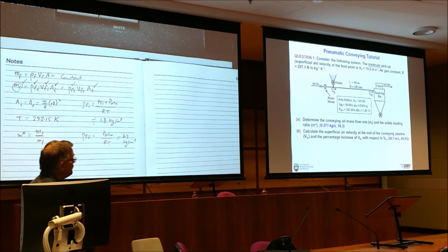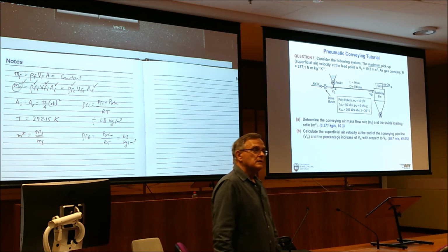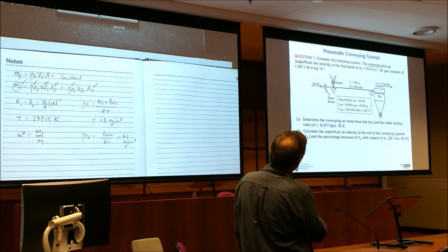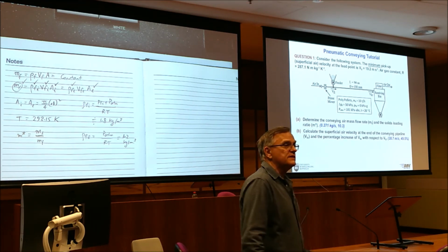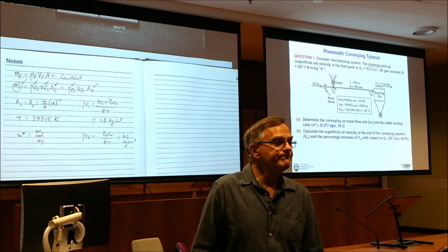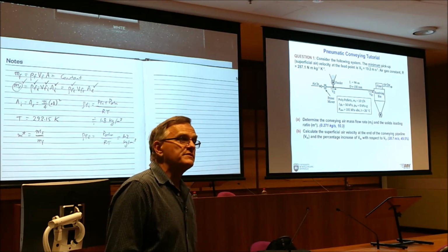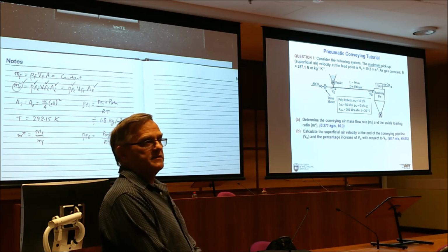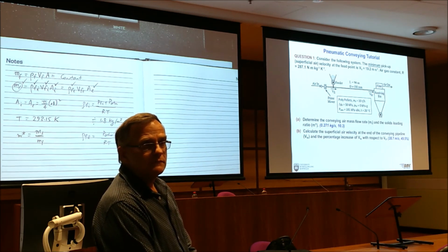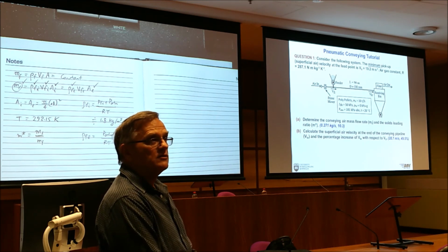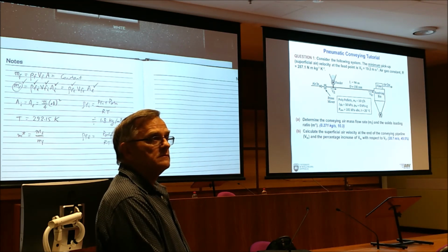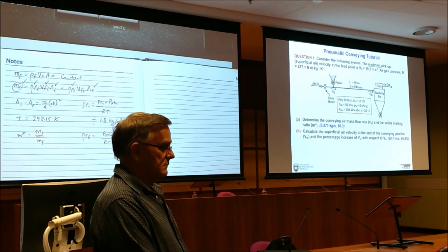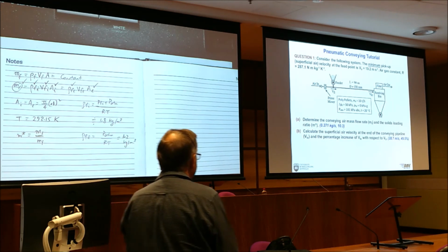28.7 metres per second. Right, so the air velocity starts off at 19.2 and it increases steadily up to 28.7. And that is almost a 50% increase, as I indicated before. If your gas density changes by 50%, your velocity will also increase by 50% due to continuity. Rho v is constant, remember that, okay? Because your areas cancel, AI equals AE. Is that all right? Any questions on that?